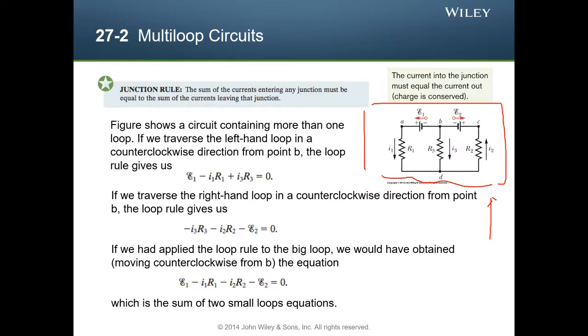So you write R3 times I1 minus I2 equals 0. Likewise, we can write it for this loop, and for this one, we have I2 and I1, and this loop is in the same direction. So we have I2 minus I1, and this is not a voltage drop, so this is minus V2 plus R2 I2 equals 0.